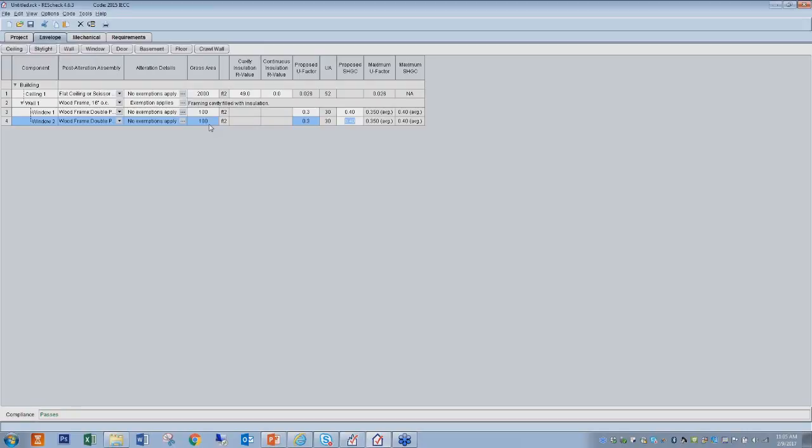And the thing to look for, there are color keys in the tools. Red means bad. Red means it's missing information, missing data. So if you see something in red, like, look, I'll remove that U factor, and it's showing it in red. I need that. Now it's saying, and down at the very bottom, it gives you little teasers, says invalid or incomplete envelope data. Go back and look, what's in red? Find it. And it's not too easy when you have 50 or 60 assemblies in there.